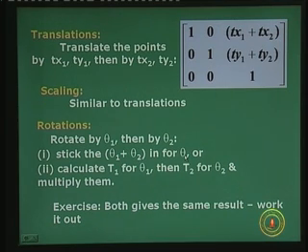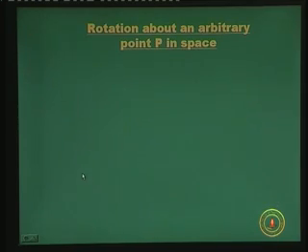where you remember you had cos theta, minus sin theta, cos theta, you instead replace that theta by theta 1 plus theta 2, and then you better do that instead of doing the second stage. That means calculate T1 for theta 1, T2 for theta 2, and then multiply them. If you multiply them, the effect which you get basically is the same as replacing theta by theta 1 plus theta 2. Take it as an exercise that both step 1 and step 2 give the same result of the rotational matrix. Okay, we will come into that form.